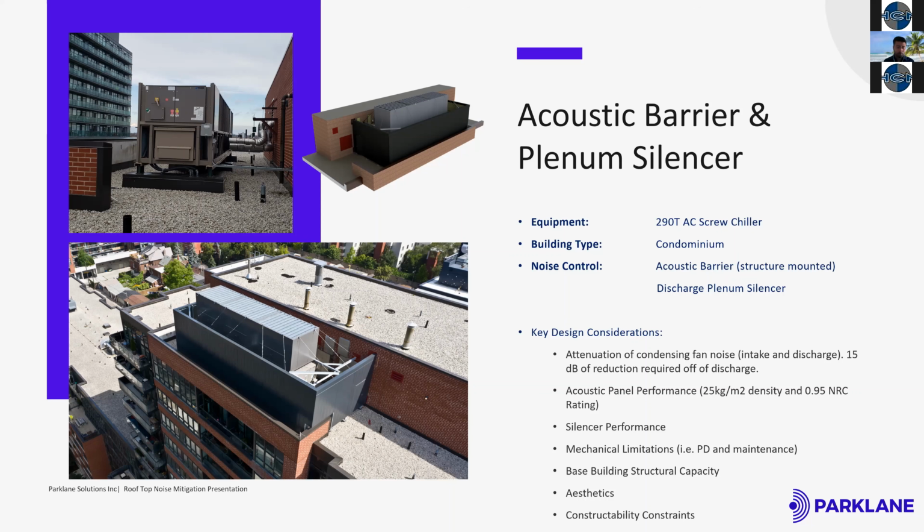When you have a rooftop unit in front of you, we could look at the performance of the rooftop unit, see the static pressure that is available, and this way we can calculate what is allowable pressure loss before the unit will start seeing difficulty with its performance. That will all be considered during the mechanical aspect of this project.